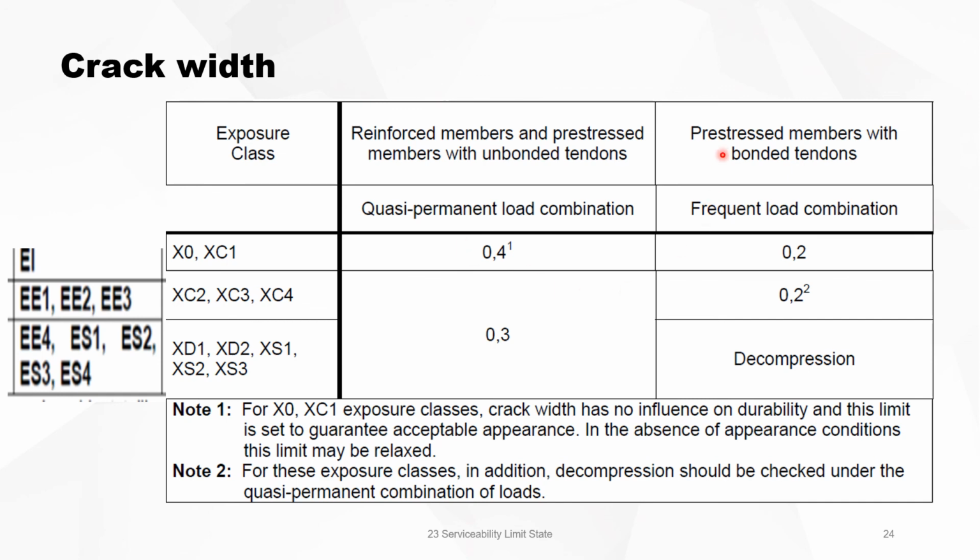For pre-stressed members, there is a checking of the decompression zone, or it's 0.2 millimeters elsewhere, under the frequent load combinations, not the quasi-permanent load.